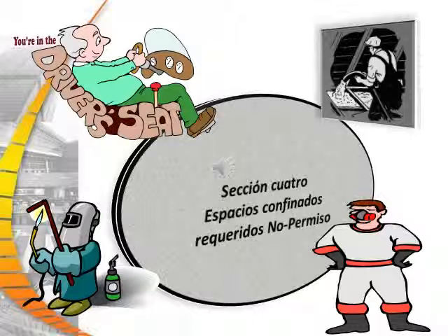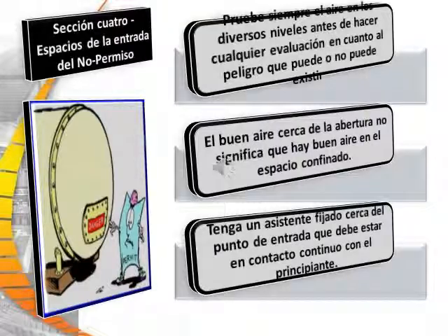Welcome to Section 4, Non-Permit Required Confined Spaces. Always test the air at various levels before making any assessment as to the danger that may or may not exist. Good air near the opening does not mean there's good air throughout the confined space.